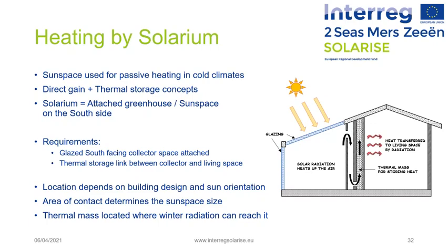A solarium essentially consists of a sun space or a greenhouse constructed on the south side of the building in the northern hemisphere, with a thick mass wall linking the two. The sun space can be used as a sit-out during days, as it allows solar radiation but keeps out the surrounding cool air. At night, it acts like a buffer space.